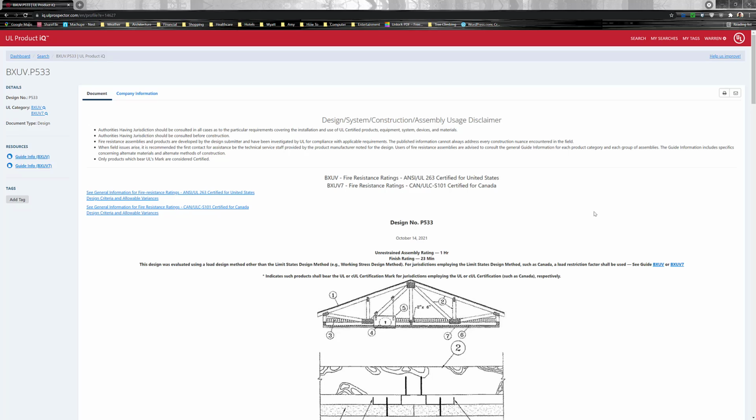Because they have to do that, ultimately that's going to make your building more expensive. Things like that buried within the Underwriters Laboratories listings are things you in general want to look out for. So if they value engineer or want to switch a product on you, sometimes you have to go back and double check that that product has been tested with the assemblies that you've chosen.